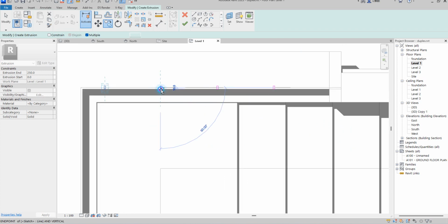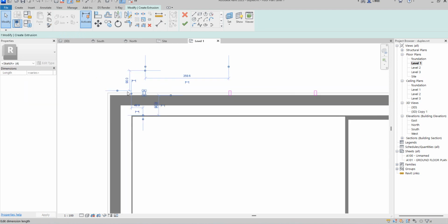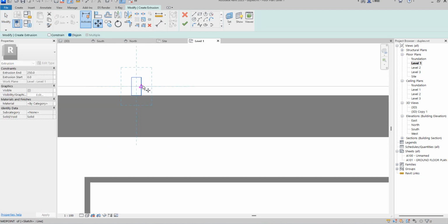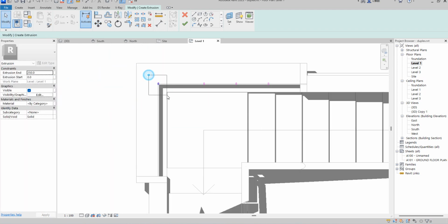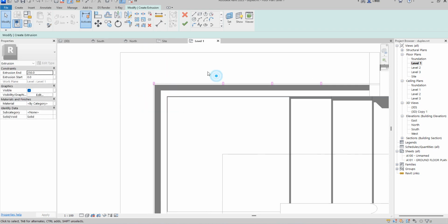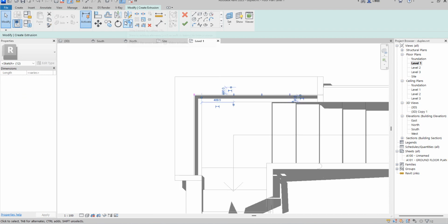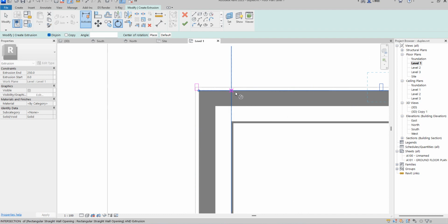So the next one you take it, so you can decide to bring this one to the very edge, to not bother yourself with too much of parameter. So now you get this one done. So what else do we need now is to copy or mirror this. Just select all, say mirror. So drag this to this point of contact. So you can rotate or do whatever you want to do. Just mirror with copy, so that will be more easy. So drop it here.